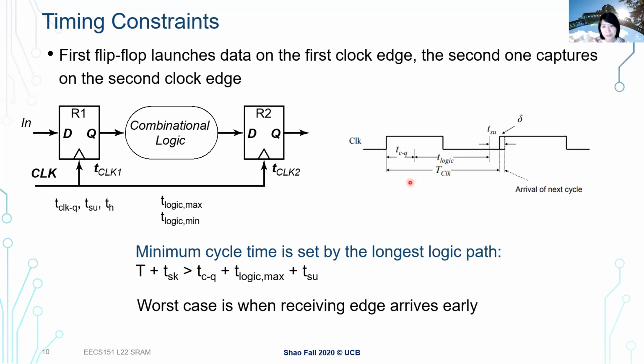So in this case, when we think about the entire clock period that we actually want to provision for this circuit, we have this clock period here, and because my second clock is arriving later, in some sense, between my first clock and second clock, I have a slightly longer time, just naturally. Not because my combinational delay is faster, not because I have a faster clock to Q delay, not because of that. Now I have a bigger buffer, a slightly longer time, just because my second clock has arrived later. So I have a longer time to process the entire information here.